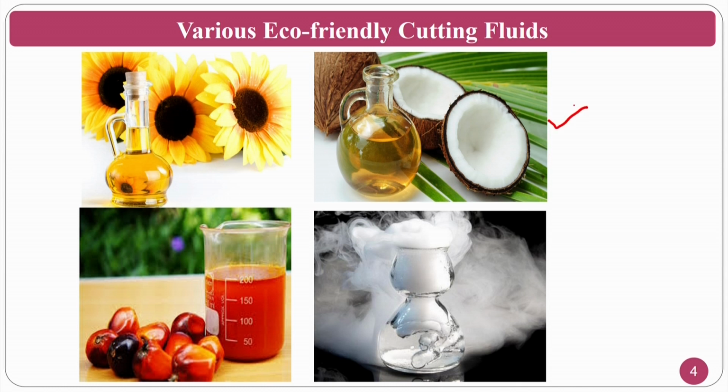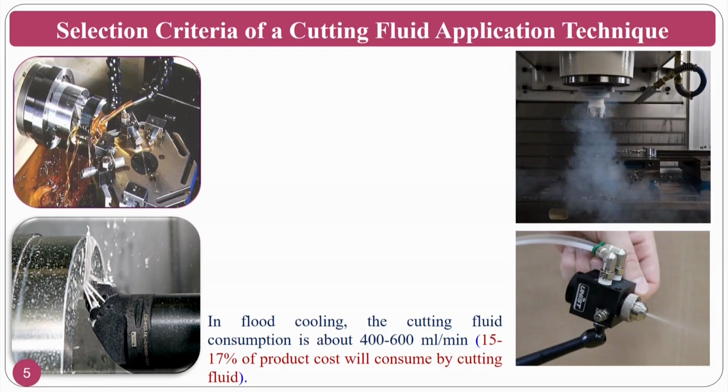Any combination of these vegetable oils, you can go ahead and form your own cutting fluid, or there are commercially available bio cutting fluids, you can procure them. Okay. If you see here, there are the solutions. Flood cooling technique, high pressure coolant technique. This is the flood cooling technique. This is the high pressure cooling, and this is the cryogenic cooling. This is MQL or MQCF.